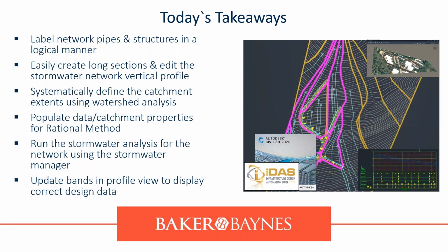Also then the grade lines for the energy and hydraulics were updated in the long section. We then updated the parts and we ticked on the update list when closing the wizard. We hit OK. And then after that, the profile, the long sections, was updated successfully with those question marks disappearing. That's where we updated the plan.